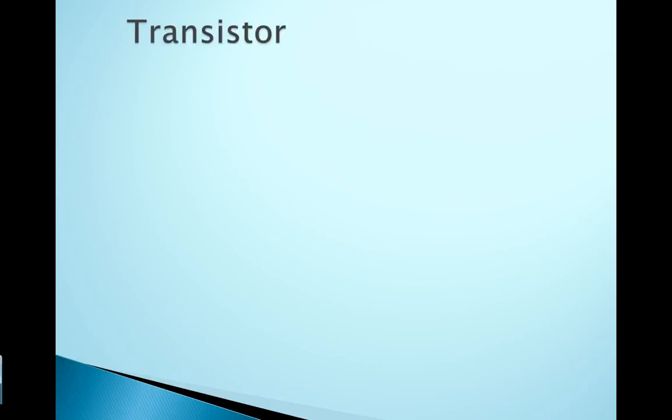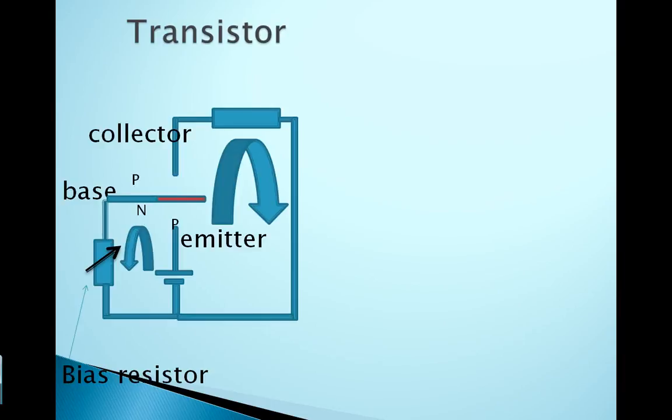Now, the transistor itself is really a current amplifier, and this is shown by the two diodes back to back. The bottom diode is the forward biased base emitter diode, and the current from the emitter, being 100%, is distributed to something like 2% to the base and 98% to the collector. So you can say in effect that the emitter current really goes through to the collector, provided the base has opened it to flow through. And therefore the current goes through the load resistor and drops the voltage across it.